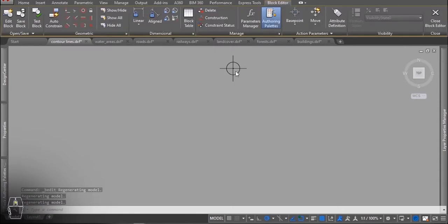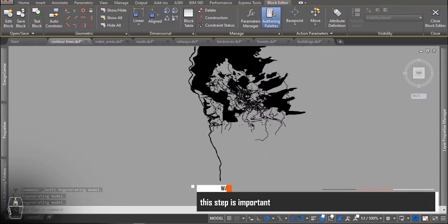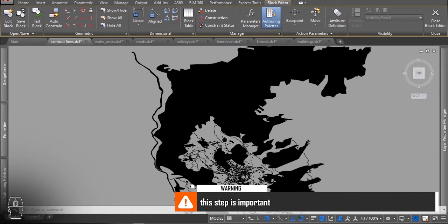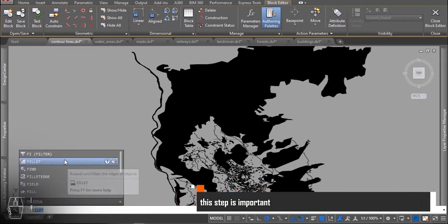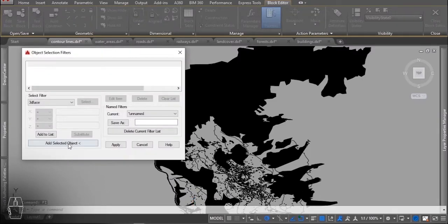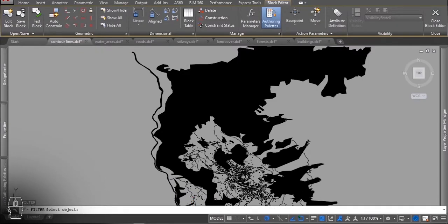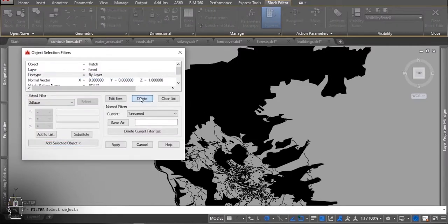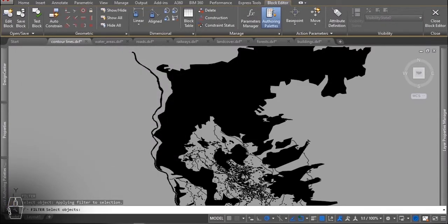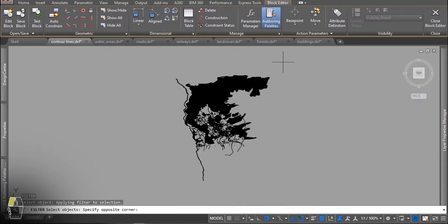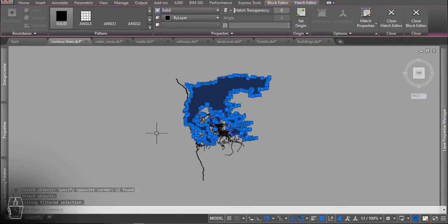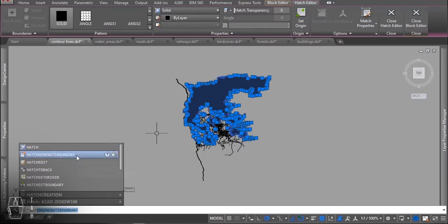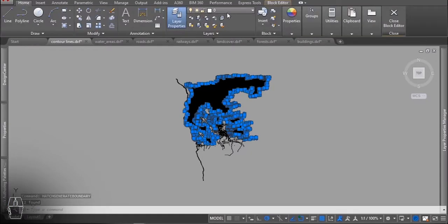Before jumping to importing things to your 3D software, you have to explode all the blocks and replace all hatches by closed polylines, because hatches are only readable by AutoCAD and cannot be properly imported to other software. You can do that by using the command hatch generate boundary in AutoCAD after entering the block editor and selecting all the hatches from each layer separately. Each time after applying the command, you have to make sure to change the layer into the corresponding one, as it will apply the default 0 layer each time you create the boundaries.